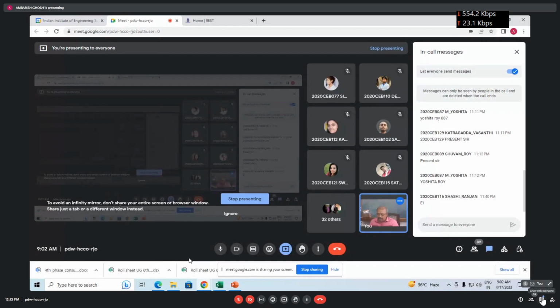And use the proper units. E will be in meganewton per meter square, I will be in meter to the power 4, K will be in meganewton per meter cube, B will be in meter, then R you will get in meter. You see the units properly in the code and use it.